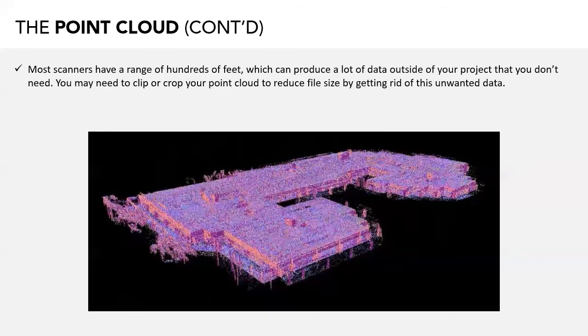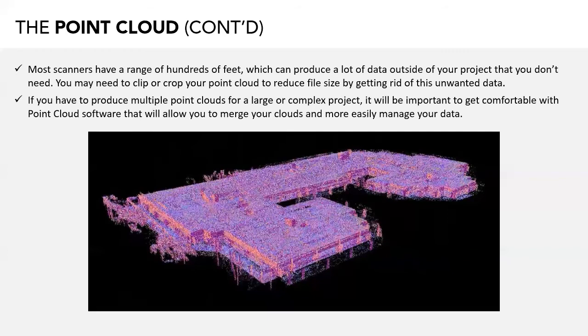So most scanners have a range of hundreds of feet, and this can produce a lot of data outside of your project that you don't need. You may sometimes need to clip or crop your point cloud to reduce file size and get rid of some of that unwanted data. If you do have to produce multiple point clouds for a large or complex project, it will be important to get comfortable with point cloud software that will allow you to merge your clouds and more easily manage your point cloud data.